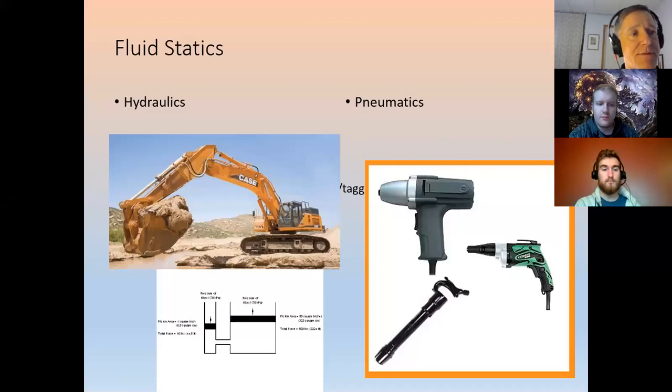Fluid statics is fluids at rest, which, in a practical sense, is used, in my world anyway, for conveying power, torque especially. A lot of twisting action in hydraulics and pneumatics. I mean, it's power too, which is just the rate of applying torque. So hydraulic and pneumatic systems. We talked about pneumatics, whether it was just air or not, and I'll say it is, and anything else has a specific name. So whether it's compressed natural gas or nitrogen systems or whatever, that's normally what we call them. So pneumatics are open-ended. You vent the air when you're done. Hydraulics, you have to return the fluid back.